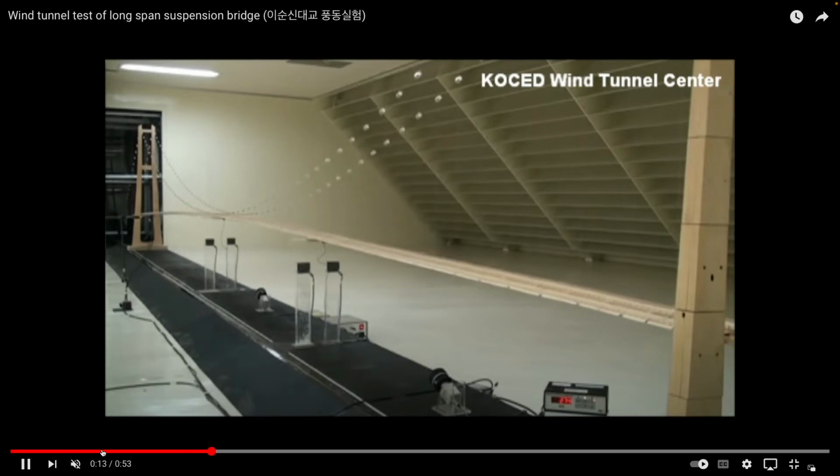We showed the Tacoma Narrows Bridge and talked about the idea that if the wind is blowing at such a velocity that it sheds vortices off the deck, top and bottom, on this so-called von Karman vortex street, then if the resonant frequency of that shedding is the same as the resonant frequency of the bridge, it just puts it in motion.